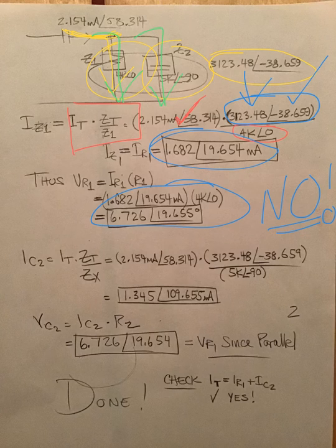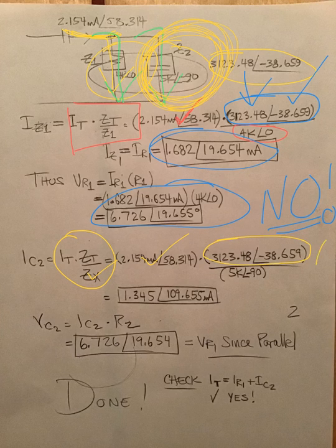And start documenting. Okay, the next thing to compute, we've got this capacitor up here at the top, the one that's in the parallel branch circled with 1,000 circles of yellow. And again, we go into the current divider down here, and IT is easy. ZX is just 5K at minus 90. It's this ZT again that'll get you in the rear. And once you figured out what it was up here, you use the same ZT. Not the ZT of the whole circuit, but the ZT of the parallel branch.